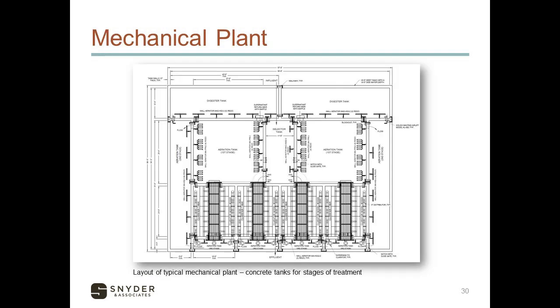As I mentioned earlier, a mechanical plant would be the most complex wastewater treatment, but once you get to a little bit larger town, perhaps a town with a little bit of industrial loading, these actually are very efficient at what they do. It's just a little bit more complex way of dealing with it. And so this is just a sample drawing. What you're seeing is the outline of concrete tanks, and they're fairly small, so the volume of storage might only be a couple of days of flow.